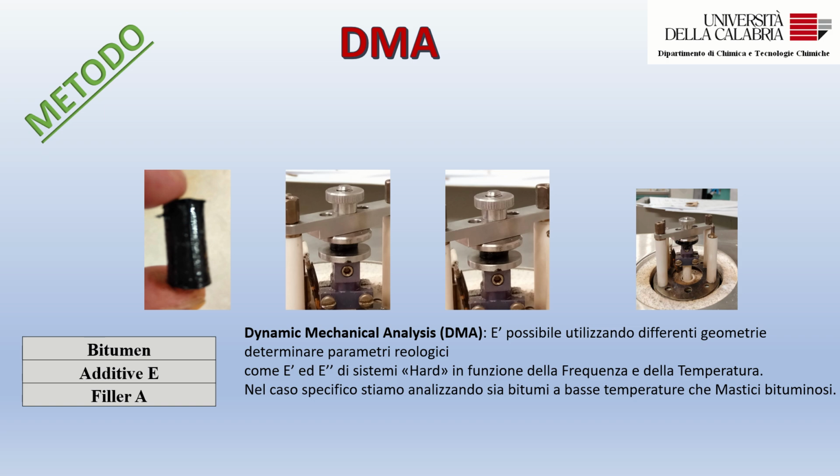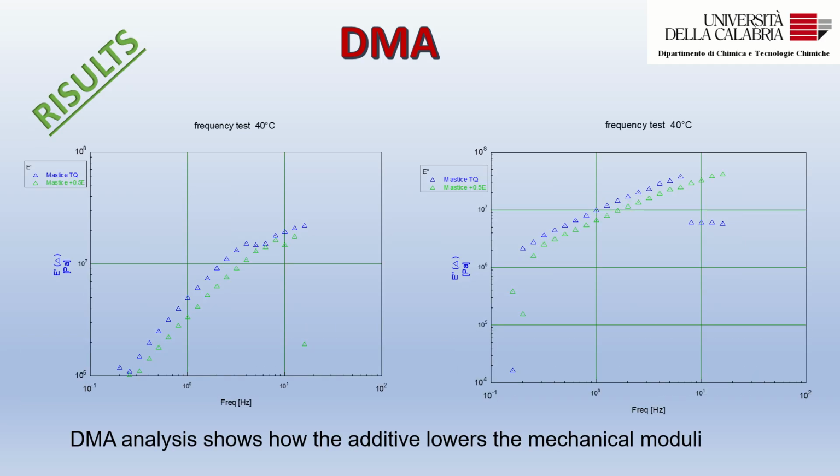The problem is this: when we analyze the data in the literature, the surfactant usually doesn't change the rheology of the bitumen in general, but changes the rheology of the asphalt concrete. So we prepare some small samples of the asphalt concrete, mixing bitumen and the filler, and we use the DMA, the rheology for the solid system, to understand if some property changes. Look here. This is the frequency sweep of the asphalt concrete, this model of asphalt concrete obtained by mixing bitumen and filler.